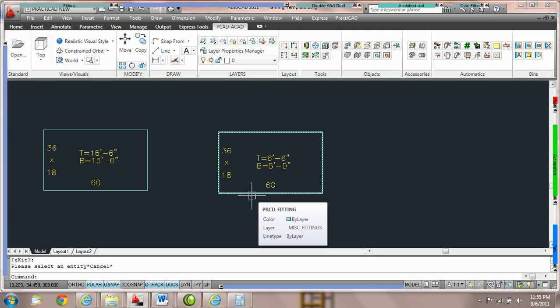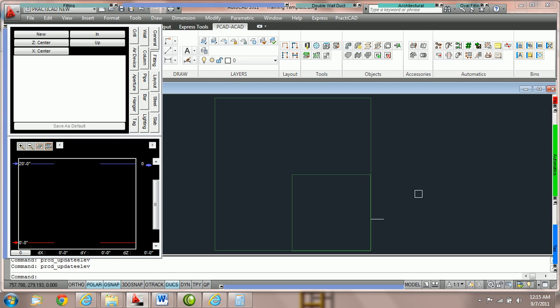design relative bottom points. In the next portion of this tutorial for the elevation box, we're going to show you how to create multiple reference points. In this particular tutorial, it's going to be multiple slab heights, and we're going to treat them as different zones where we run duct over both of them, but some duct needs to be tagged to this first reference point, some duct needs to be tagged over the second reference point.